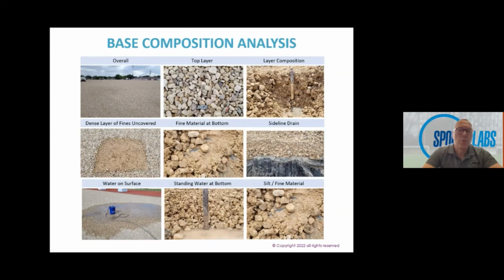And then you can see a few more here. So a couple of things just to pick up. We've got a nice shot of a material that looks perfectly fine on the left hand side. You scrape off the levelling layer and you can see you've got a very dense impermeable material, which is supposed to be vertically draining, and then when you do a test on it you can see a massive pond of water forming around it, and it's just going nowhere. And you know, lay turf over that, you're going to have significant drainage issues when it's inclement weather.